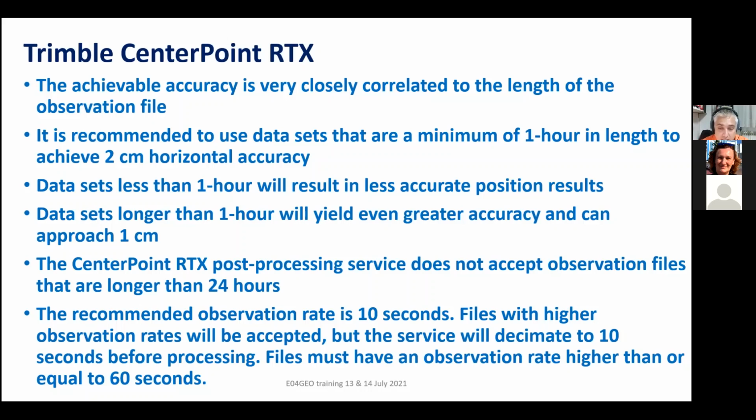And files must have an observation rate higher than or equal to 60 seconds. So if you provide your data, let's say, at a 2 minute logging rate, the files will not be accepted, since those logging rates do not guarantee the achievable accuracy.